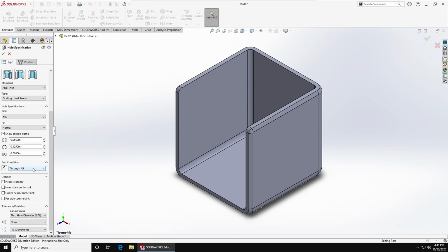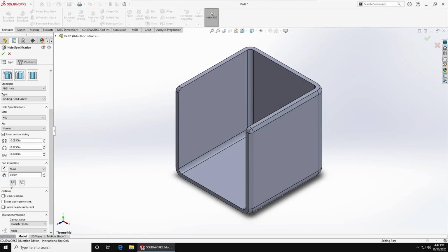Finally, down at the bottom, we can select our end condition. This works exactly the same as the end conditions for standard extrude cuts, with one new wrinkle. While using a blind end condition, we can choose if the given distance defines the depth to the tip of the hole or the depth to the shoulder. One thing that you'll notice is missing on this menu is something to define the angle of that little cone at the bottom. That is because the cone is chosen to match up with the angle of the standard drill bit, or approximately 118 degrees. After you've already positioned and finalized your hole wizard, you can sometimes go back and change it when you're using the blind end condition. But for our purposes, if something does allow you to set the angle at the bottom, you can always leave it at 118 degrees.